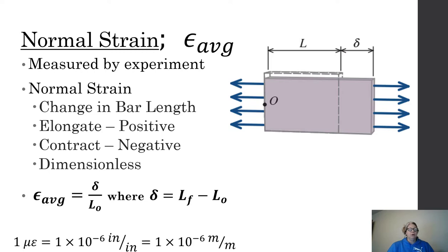And we can talk about microstrains. What is a microstrain? I've never heard of that. It's just basically e to the negative 6. Instead of having 0.000475, we could call it 475 microstrain, inch per inch. So we're not writing very long decimal numbers, okay? It's just times 10 to the negative 6. You can put it with inches, you can put it with meters, it doesn't matter. I don't want to have little teeny tiny decimals, so I can write it as a bigger number, 135 microstrain. I know it's really 135 times 10 to the negative 6. Those of you in strengths lab, you probably have already been doing this.